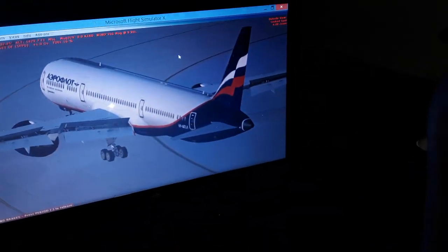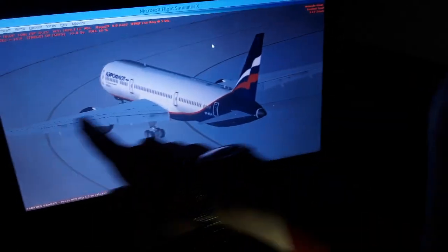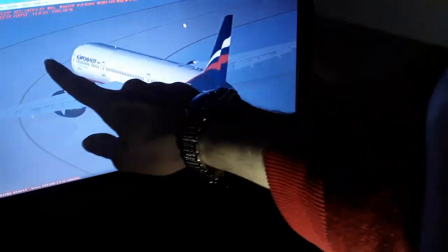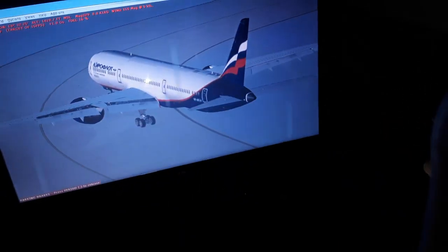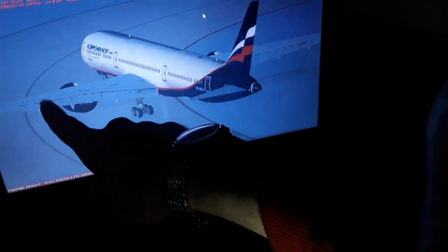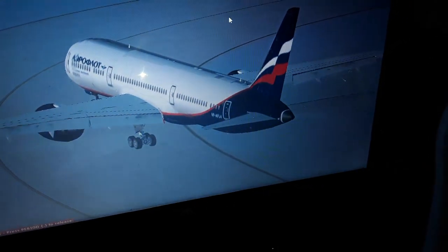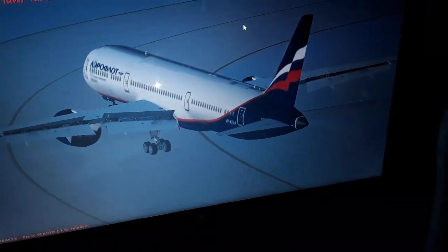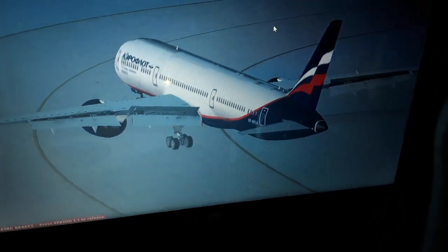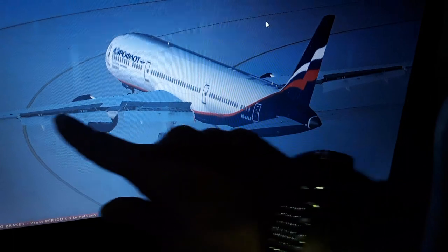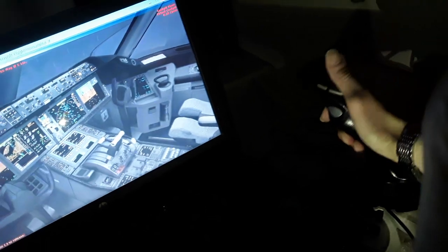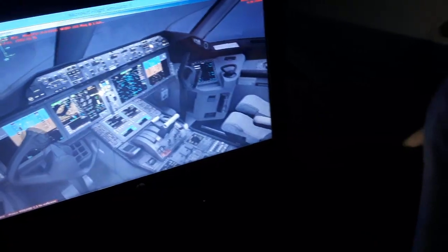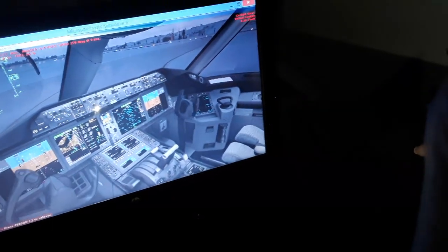Also we have over here the ailerons and the spoilers, as you can see. We have one more axis from nose to tail, the longitudinal axis or roll axis. We can use ailerons, spoilers, left and right side stick in the Airbus like this. In the Boeing, we use the differential air pressure between the left and right wing like this to make the aircraft roll either left or right. You can see spoilers all extended and the flaps and the speed brakes and the slats extended. So we use a control wheel in the Boeing to make left and right turns like this, very easy to remember, no difference.